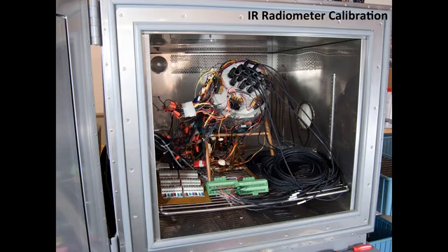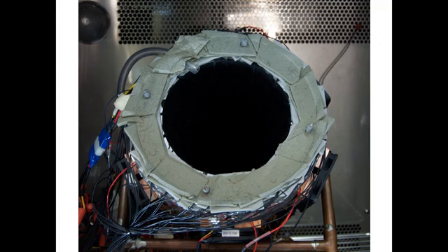The final component that's essential for an infrared radiometer is the calibration. The photo that you're viewing now is a picture of the calibration system at Apogee Instruments. So there's two main components. The one that I've circled here is the actual cap piece where all the radiometers are held during the calibration procedure. The cap piece is mounted on top of this piece here, which is the actual blackbody cone or radiation source. What happens during calibration is the radiometers are mounted in the cap piece over top of the cone, and you can see some insulation around the cone there.